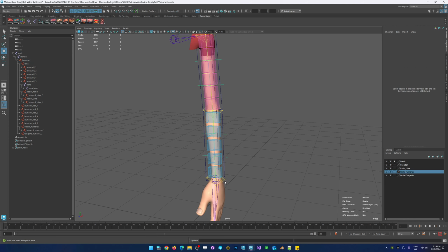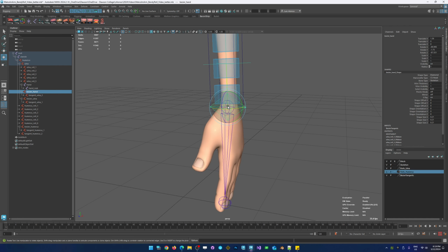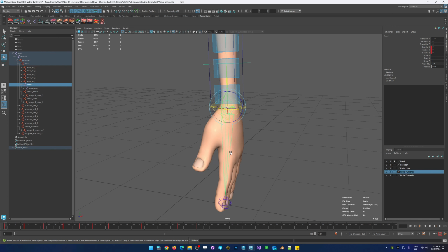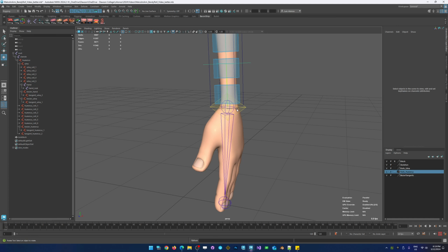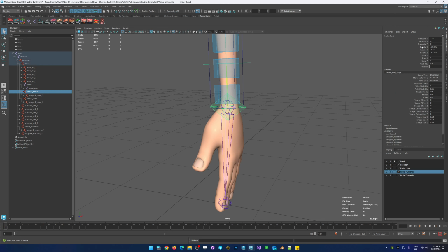Now the other thing here is that this object over here, when you rotate it, has a built-in twist action. However, just like we talked about before, this needs to turn based on this object. We've gone through multiple methods, and we've learned that the best method is using some form of quaternion-based roll. First of all, I'm just going to double check here. I think I need to freeze this object for rotation. So I'm just going to go Align, freeze zero to joint orient. So now that's been zeroed out.